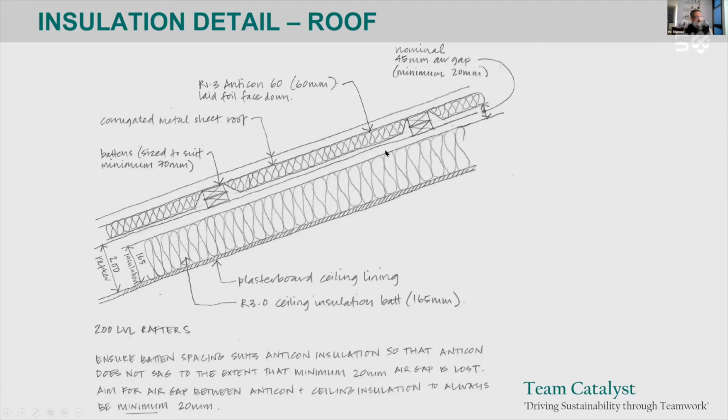So I devised an air gap between the two layers, and actually it's open on both sides. So there's a little stream of air going past, and I'm hoping that the condensation won't fall onto the insulation. We'll see in 5 years' time, but that was the building physics which allowed us to do that. It wouldn't be the model to do that.